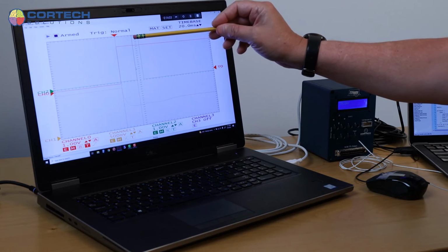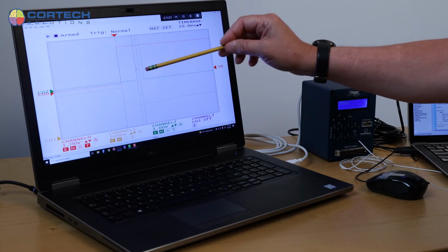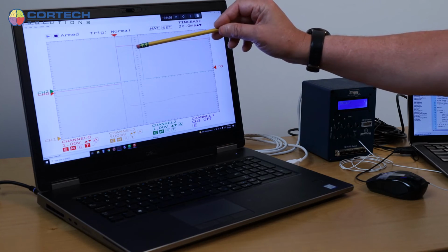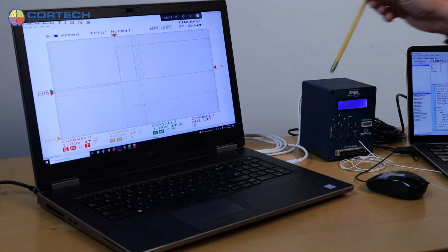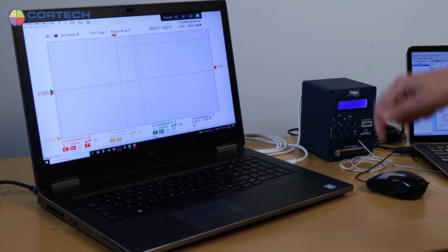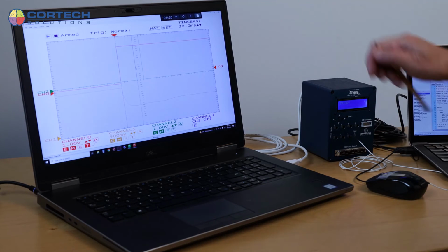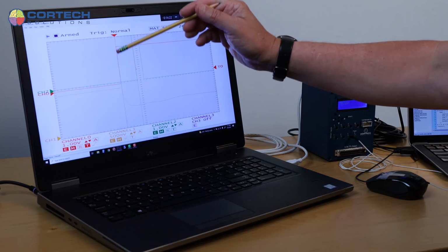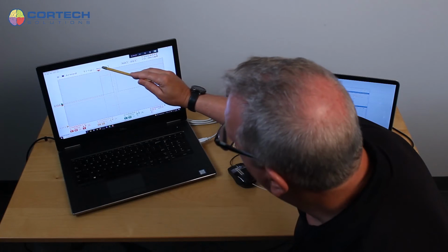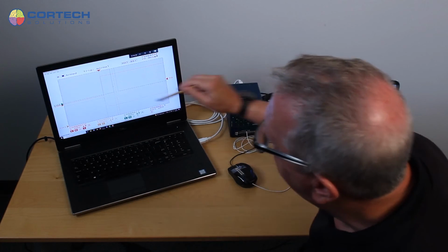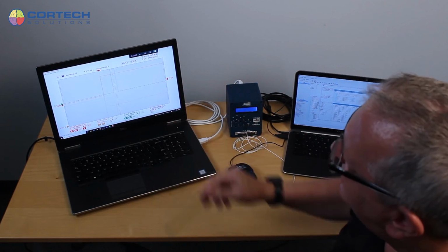So if you want these event markers in your EEG or eye tracking or other data to be perfectly aligned with the actual pressing of the button, you're much better off either using Triggy with a pressure sensor or the Triggy response device, which will be similarly timed with respect to the actual event and not delayed on the order of 20 milliseconds because of the computer trying to interpret and understand the response before it sends out an event marker.